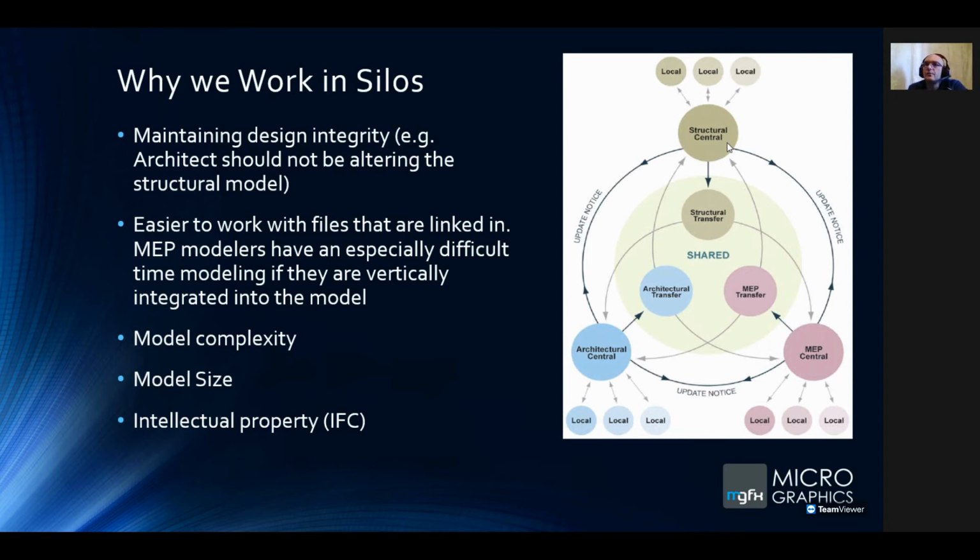And I said to the guys, look, this is never going to work. It's not that I'm doing this on purpose. It's happening by accident. I'm trying my level best not to select your elements, but it's happening. So unless you want further complications and chaos in your model, let's split the models from each other. Let's link them in. And that achieved great success, because not only was the model more responsive, but I was unable to delete the architect's elements.